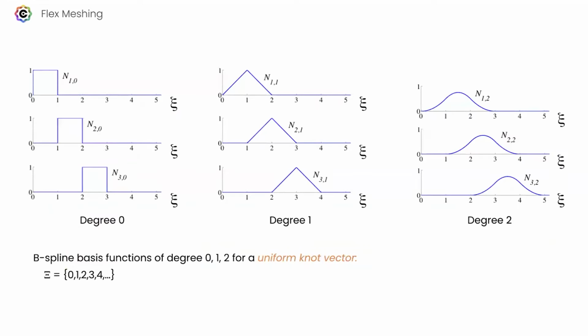And like I say, traditional FEA uses primarily these linear hat functions, and we use higher order spline functions. So this is what these little quadratic B-spline functions look like. So you can see that they have a little bit wider support, and they're continuous. The first derivative of these functions is continuous across these element boundaries.